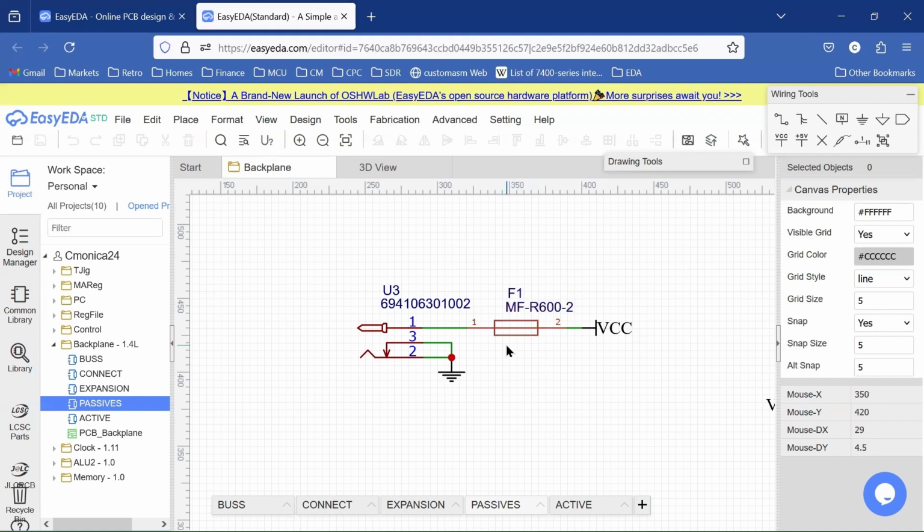We haven't really talked about what that resettable fuse is, but essentially it's a variable resistor, and the resistor changes its resistance based on the temperature of the resistor and the material. It's better known as a thermistor. And this is a special kind of thermistor called a PTC thermistor, and PTC stands for positive temperature coefficient. What that means is that the resistance on this thermistor goes up as the temperature of the material or the resistor increases. So that's pretty much what we want in a resettable fuse.